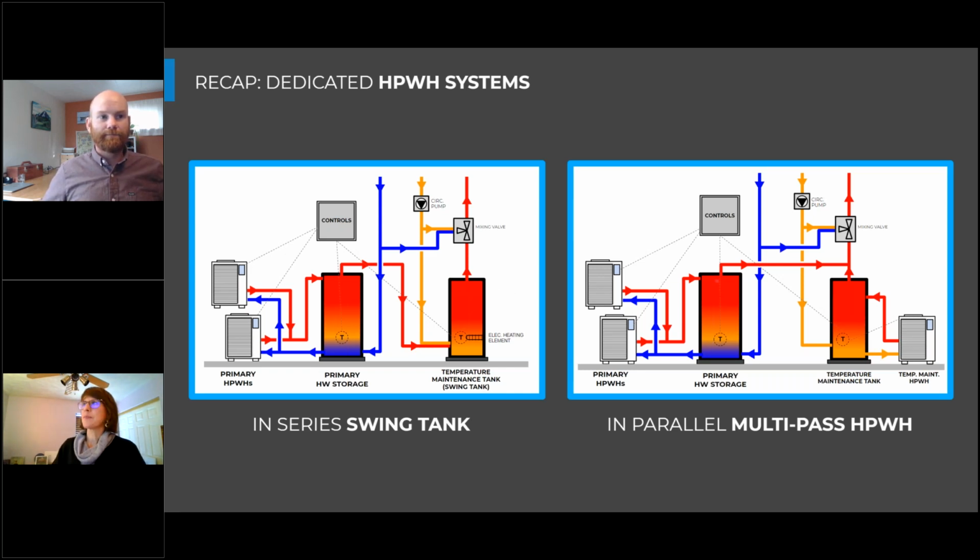So here's a question. When you have multiple primary tanks, are they always in series? So for single pass equipment, they are typically, if not always, in series. For multi-pass equipment, multi-pass primary heat pump water heaters, you may and likely will want to connect those in parallel.